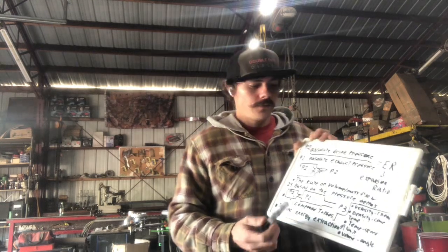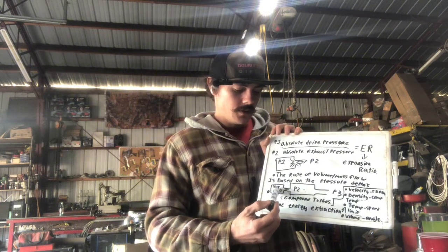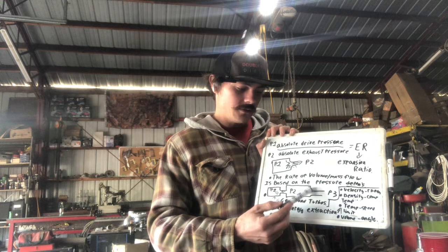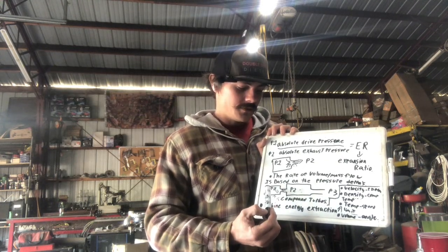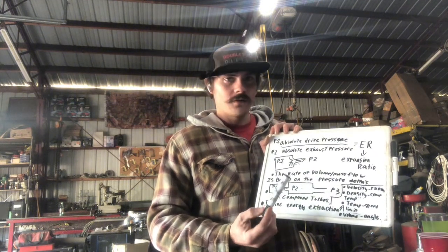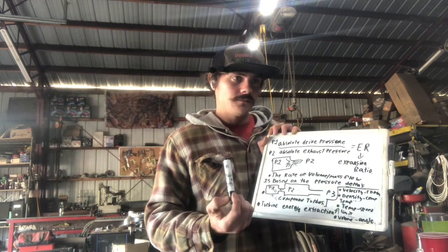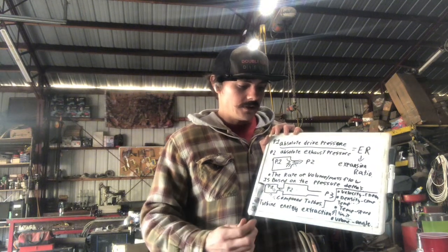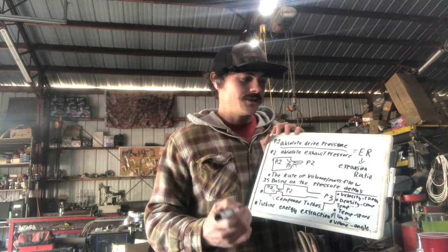As far as screw-ups go, I know about this because I've screwed it up quite a few times, where I make P1 flow too much without making sure P2 flows enough on the atmo turbine side, and the system's terrible. It runs like garbage every single time. It was really confusing at first until this made sense. It seems really simple now to think about, but at the time it didn't. But you can watch this happen, which makes it cool.